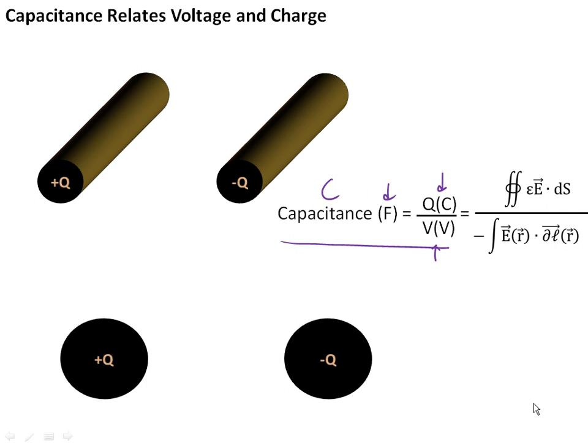And now you start to see some of the use of electromagnetics: you use this to calculate things that matter in building circuits, like capacitance. And you have to understand what we mean by geometry here. Geometry is not just the spatial arrangement of these wires. For example, I would get a different capacitance if I use square wires rather than round wires. But because we're talking about the flux vector to calculate Q, in other words, we use epsilon E, it also matters the materials that are around and surround these wires.